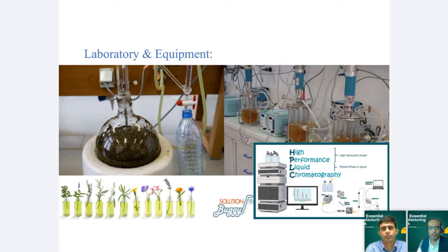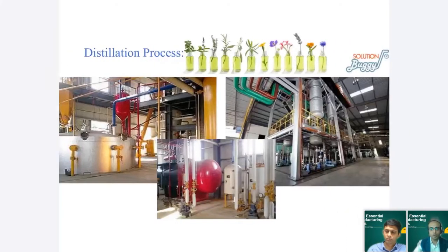General laboratory equipment required includes flasks, glassware, a boiling chamber, crucibles, and distillation assemblies of 2 to 5 liters. If you do want a more precise product, a 50-liter distillation assembly and a 20-liter distillation assembly, and a rota assembly will sometimes be required depending on the product. HPLC is a must to control quality properly on our developed product, because the quality performance and the contaminant or impurity profiles will definitely affect the selling prices. So a quality control lab is definitely a good option when we are manufacturing this kind of unit.